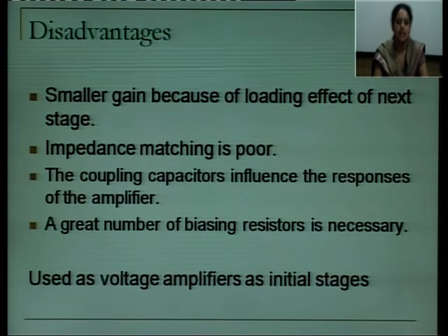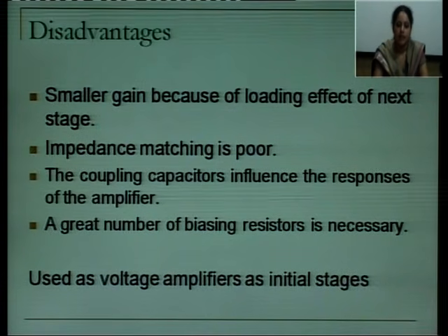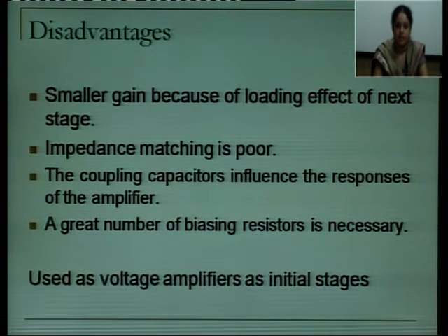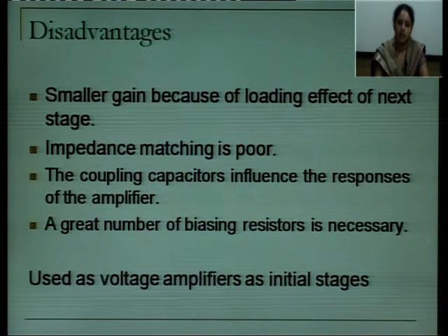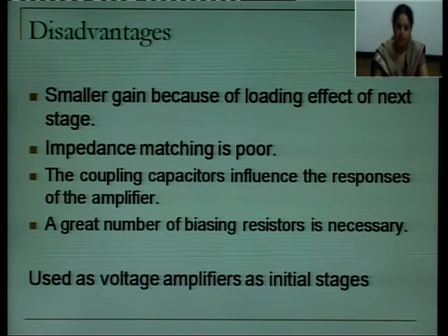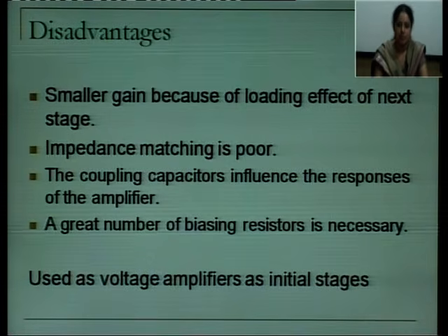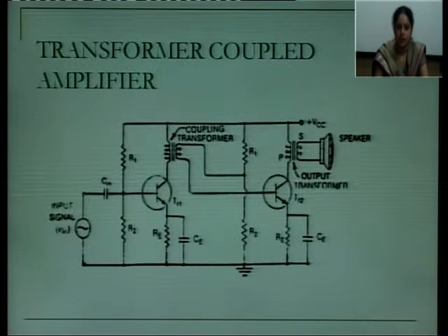The coupling capacitors influence the responses of the amplifier. A great number of biasing resistors is necessary, and the application of your RC coupled multi-stage amplifier is that it is used as a voltage amplifier in the initial stages of your circuit.